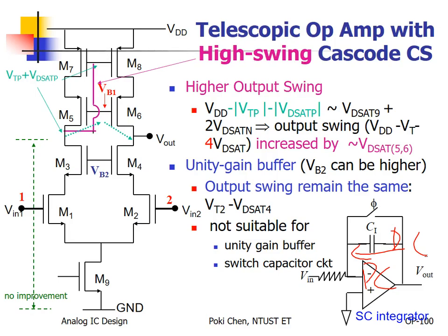So the DC current caused by DC input offset will flow in this way or in that way. But anyway, you can see the voltage of the capacitor will be saturated. For example, if the current flows in this direction, then the output voltage will be pushed higher, higher, and higher, right? Finally, it reaches at most VDD. That's it, no more. After saturation, it will become malfunctional.